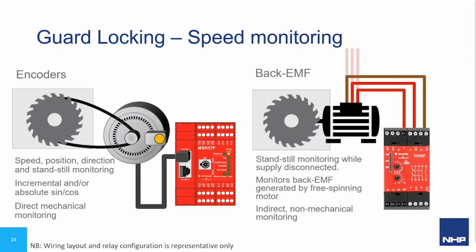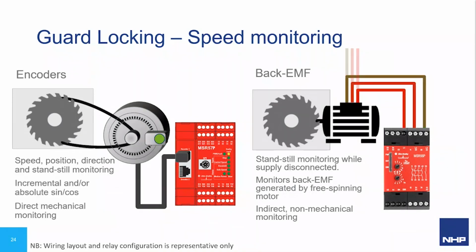Safe speed monitoring can also be achieved through other means, both directly and indirectly. Some high-end safety monitoring relays are capable of using one or more encoders to directly monitor the speed of the load. However, given the nature of encoders, they can also be used for additional motion-based safety parameters, whereas the use of proximity sensors will typically only provide the speed.